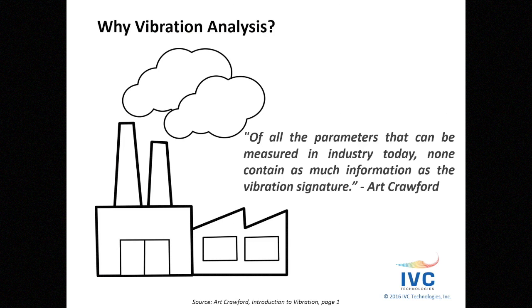And Art said, of all the parameters that can be measured in industry today, none contain as much information as the vibration signature. In all my years of testing, I've found this to really be true. The biggest reason is, regardless of what happens in process or production, if anything changes, typically the vibration signature reflects that. If temperature changes, the vibe signature will change. If the product that you're running changes, again, the vibration signature will probably change. Even if you change something as simple as the operators, there can be a change in the vibration signature.